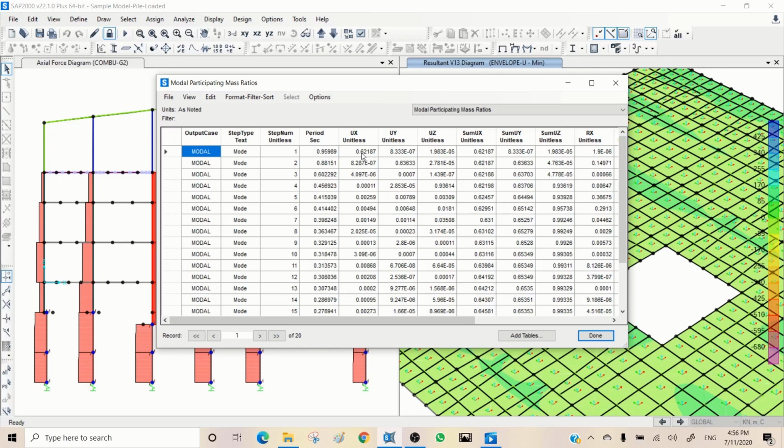It really goes back to you, if there is any provision in your standard or not. If they said no, if you know that the period is less, that means the structure is stiffer, then you need to use this modal analysis result for your calculation. You will end up with more base shear. In Australia, we don't have any clear provision about that. I personally try to be conservative all the time if it's not a significant impact on the cost of construction. It really depends on the importance of a structure as well. Guys, those are just numbers. You need to make a decision on what is the safe and sustainable way and align with your code of ethics in engineering and use them. So this is basically what I wanted to share for modal.